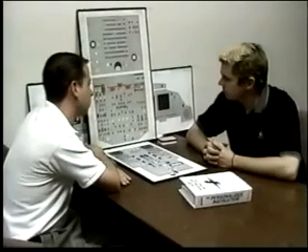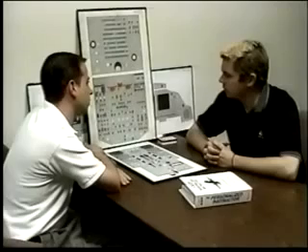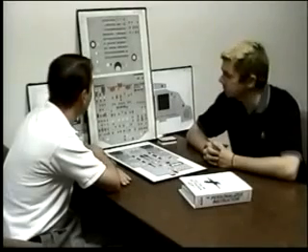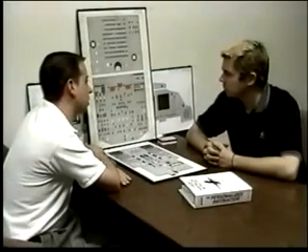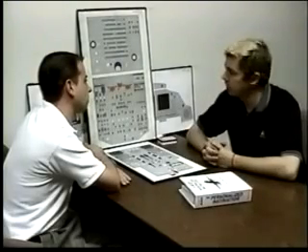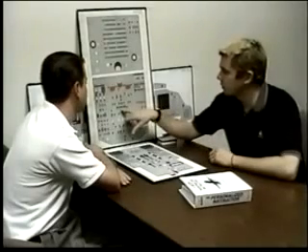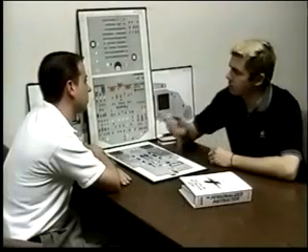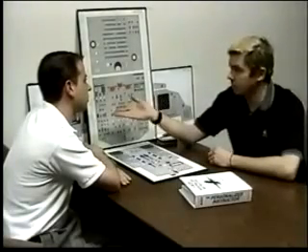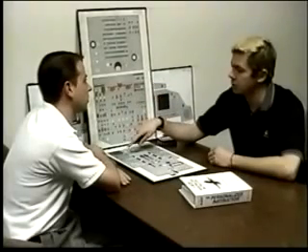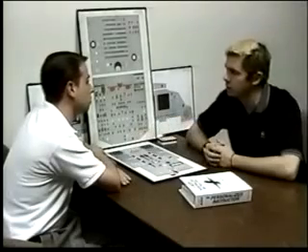What powers the emergency generator? The emergency generator is turned by blue hydraulic pressure, and that pressure is maintained by the ram air turbine that's pressurizing the system. And what do you have available now as far as displays and buses? Well, once the emergency generator comes online, you've got 4 buses and therefore 4 displays. The 4 buses are the essential AC in its shed and the essential DC in its shed. The 4 displays are the captain's PFD, the captain's ND, the upper ECAM, and the number 1 or the captain's MCDU. You still also have the RMP and the 2 ACPs.